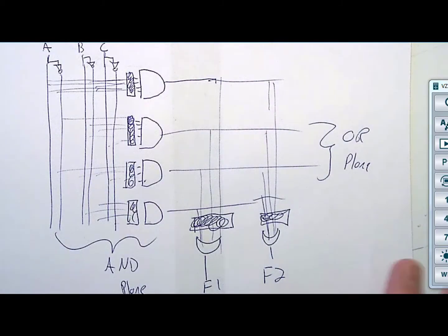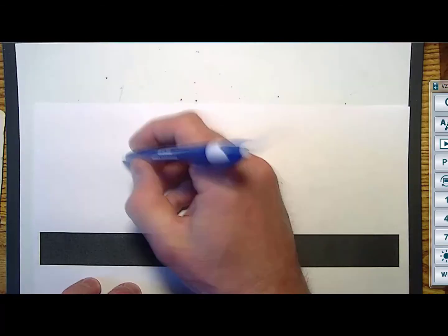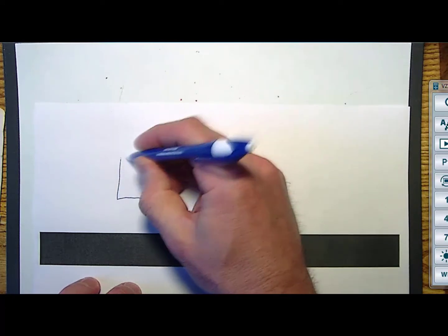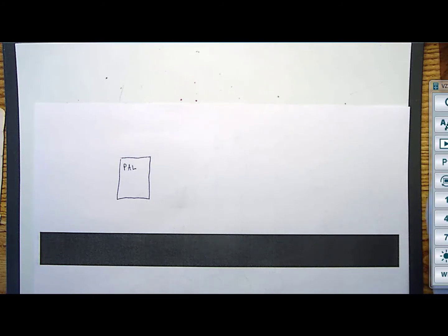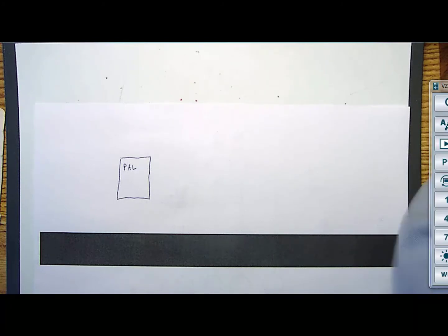Now you're like, man, this is sweet. So you have a programmable array logic, a PAL, and this creates combinational logic. What immediately do you want to do? Everybody's building finite state machines. So you would have a D flip-flop component, just like you used in 261, and then you would have these PALs, which were awesome because they would give you these logic expressions. So you could build a finite state machine and use PALs for your next state logic and for your output logic, but you were still putting D flip-flops down and building pretty big circuits. And that's how the first digital systems were made.